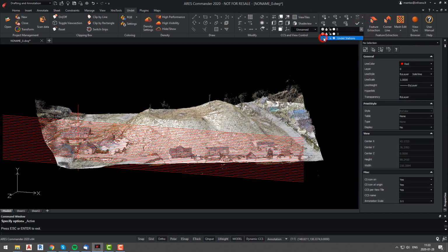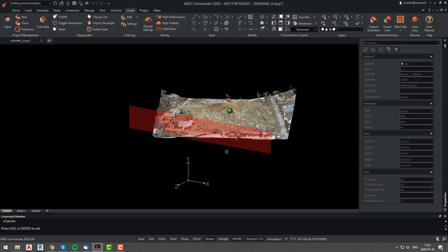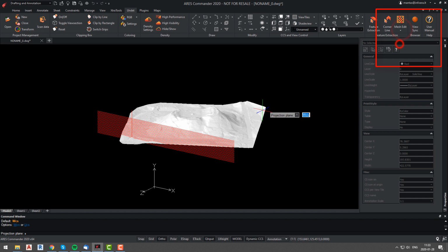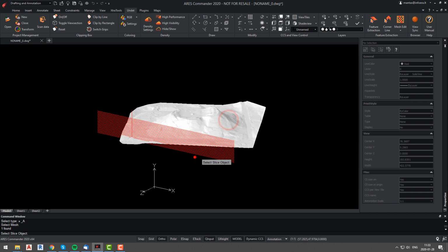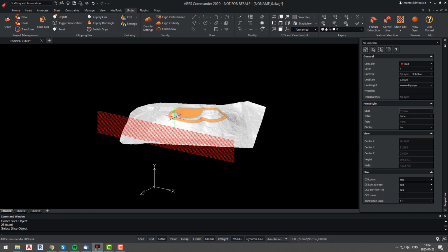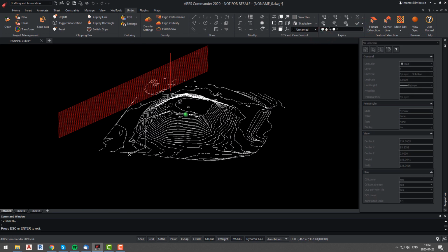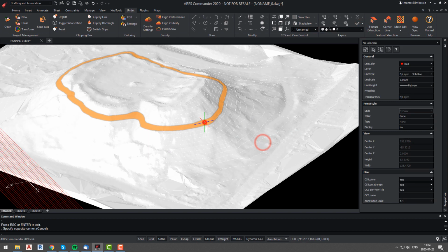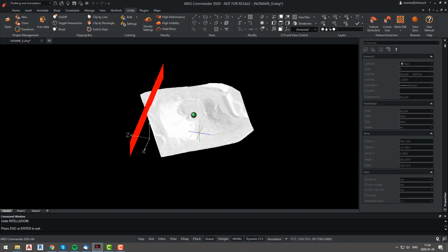We will turn off point cloud, and we will run mesh slice imprint function. This time we will select UCS for user coordinate system, since we want to generate contour lines from our elevation view, and we will use project and slice function. Once again we will select mesh, and then select lines which will generate our hill contour mesh. Mesh was sliced precisely according to our lines and generated projections are precisely at the same spots.